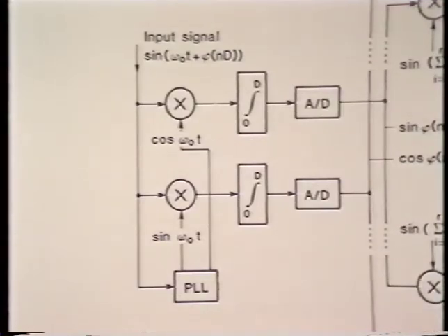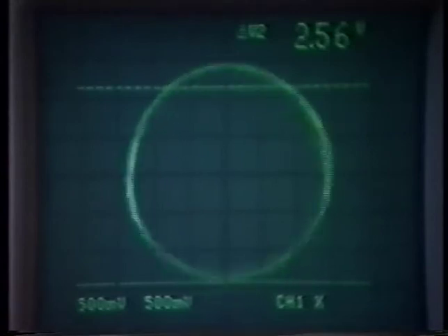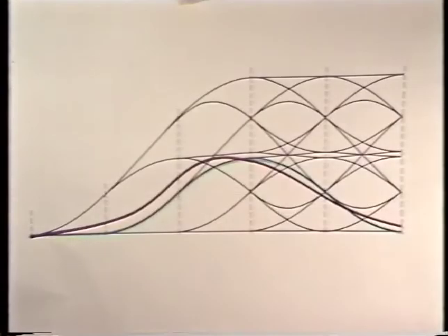The input module of the receiver is a coherent phase lock loop which regenerates a carrier by first doubling the non-existing residual carrier component and then performing coherent demodulation, followed by AD conversion in phase and quadrature. When coherent synchronism has been achieved, the circle will stop rotating.